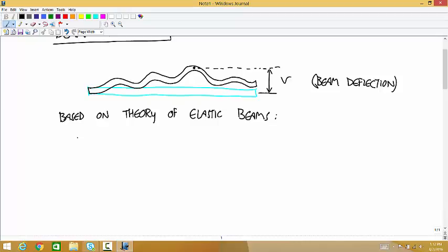that if you take the bending moment and divide it by the Young's modulus times the area moment of inertia, that's equal to the curvature of the beam at that location. This equation is true point to point, so this is true at a single location, true at every point.